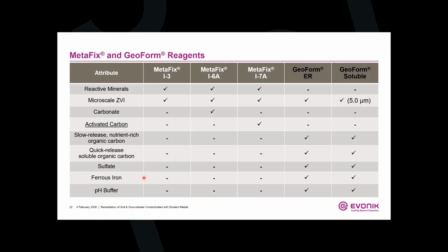These reactive minerals are fine-grained powders that provide slowly released ferrous iron and slowly released sulfide, and also have surface charges, so they will concentrate reactants at their surfaces because of charge interactions. These three Metafix reagents also contain a substantial amount of microscale ZVI, which everyone understands. It's a powerful reducing agent, produces some alkalinity, and will slowly release ferrous iron over a period of years.